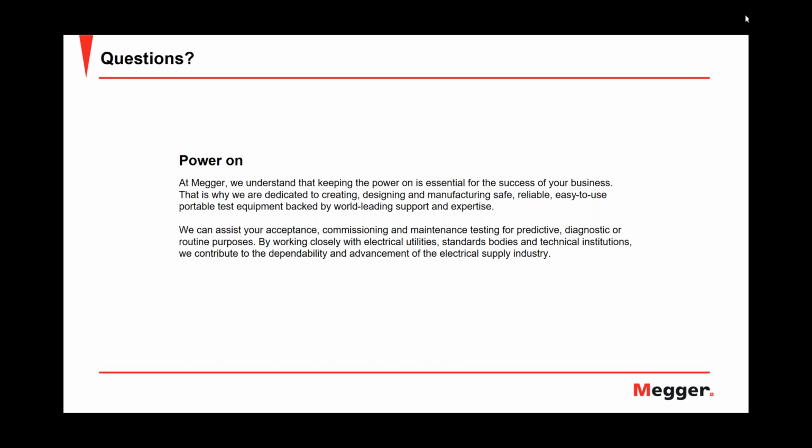But there is also always another way to verify this. If you see an open and you're not sure, is it the end? Is it an open conductor or could it be an open neutral? If you don't know, you go to the other end and you short the conductor to the neutral. If you see no change on your TDR screen, you're not looking at the cable end, but you must be having an open, either open conductor or open neutral. That is the confirmation of that situation.